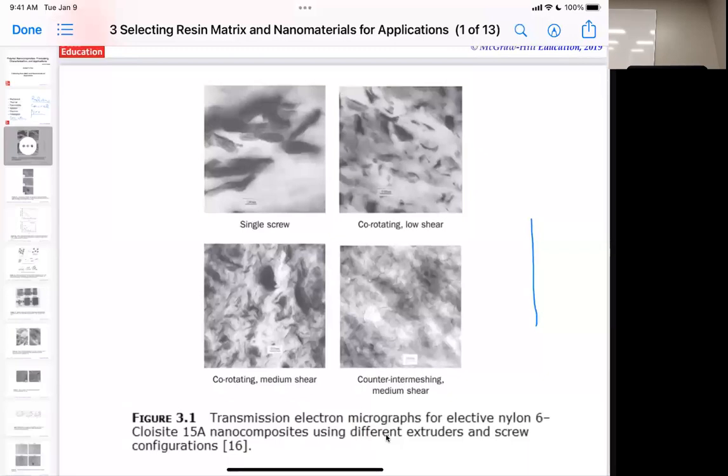Okay, and the viscosity changes with heat, right? Yes. Yeah, there's some ranges that you can do. You have to have a minimum viscosity to get your pellets to melt, but then your shear might be too high, you might destroy your polymer. So you have to have a low enough shear, a high enough heat, so the polymer melts enough so that it's not destroyed by the shear, and it's not so high that you're thermally degrading it.